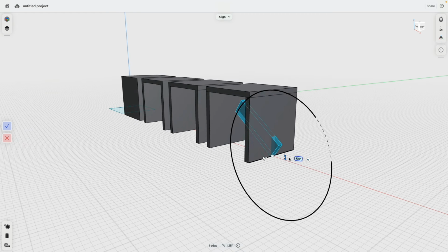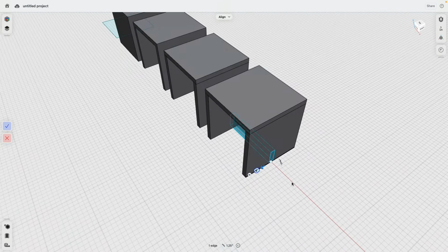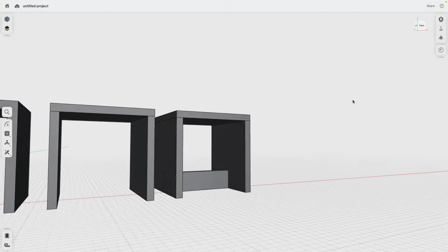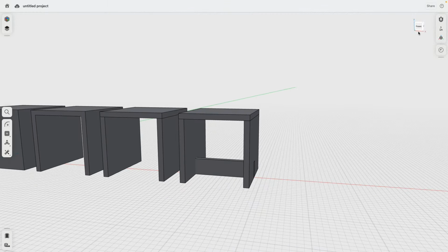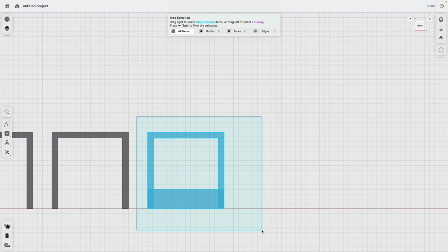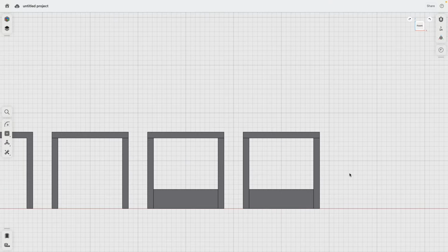Now we can rotate elements around. We can snap them to endpoints, midpoints, and I just keep this centered. Perfect. So this is kind of like how the thing could look at the bottom. Let's go to a front view, left click to the right, copy, 20 inches.